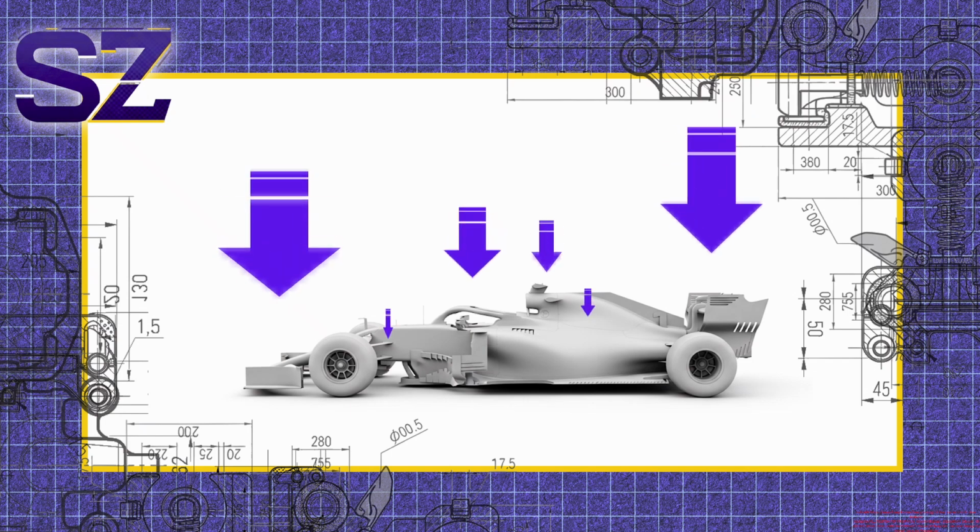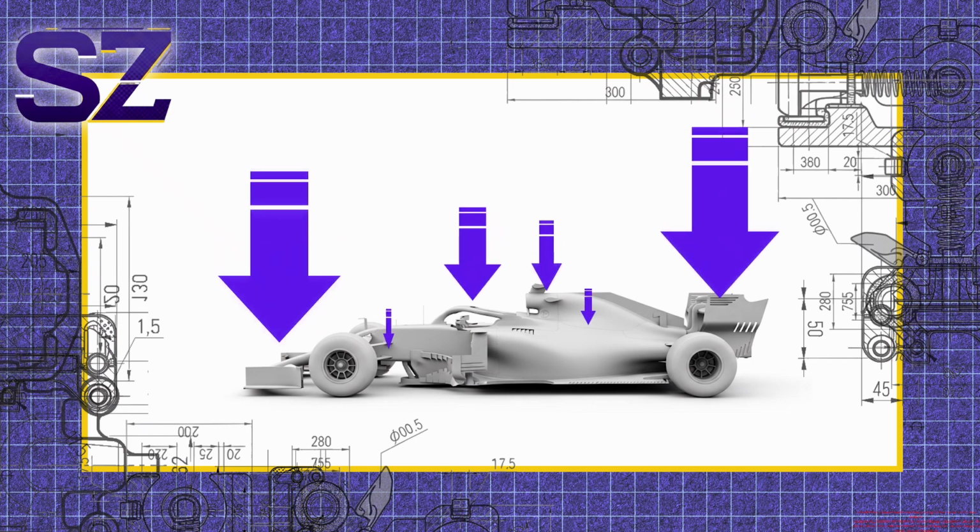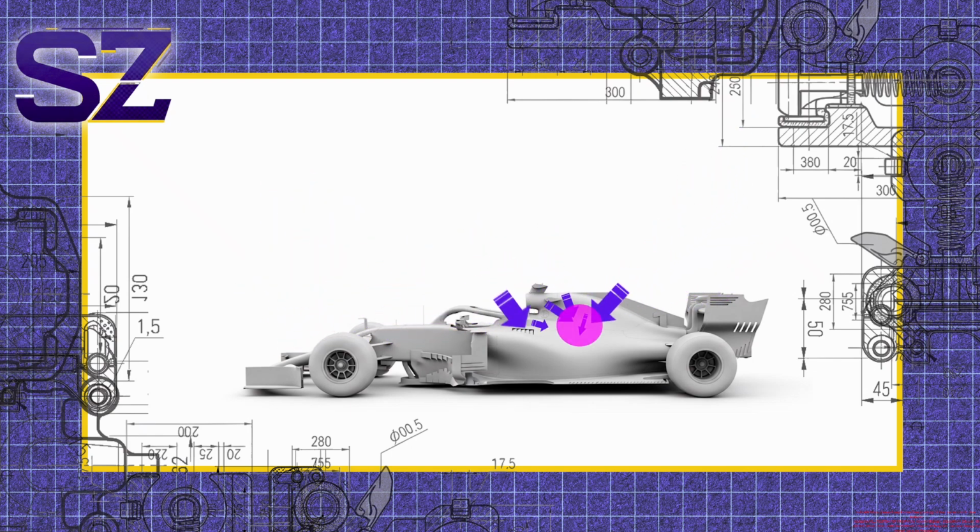Next is the aerodynamic consideration. The car's downforce isn't applied evenly across the whole car, it's distributed. The balance point for the aero forces is called the center of pressure. It's the point where all the aerodynamic forces effectively act, and where they produce no net torque on the car. Meanwhile, the center of mass defines where the mechanical load transfers around. When both are aligned, the car is predictable, but when they're mismatched, things start to get tricky.